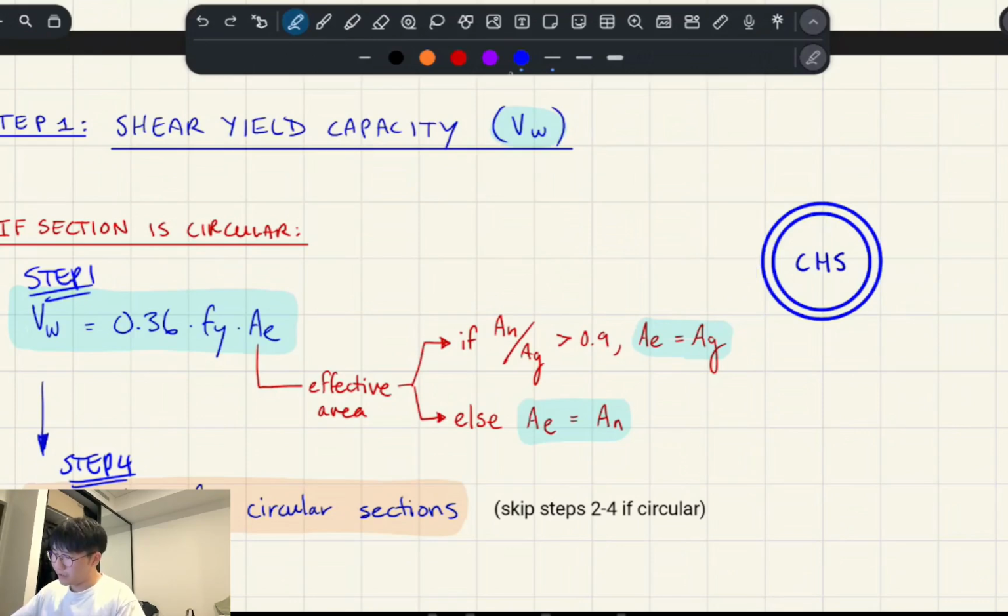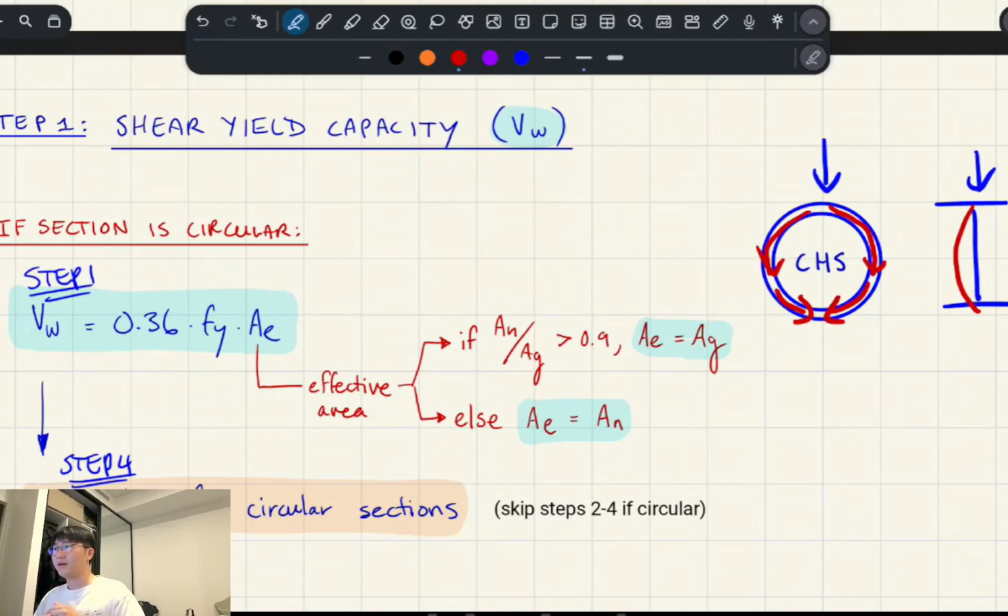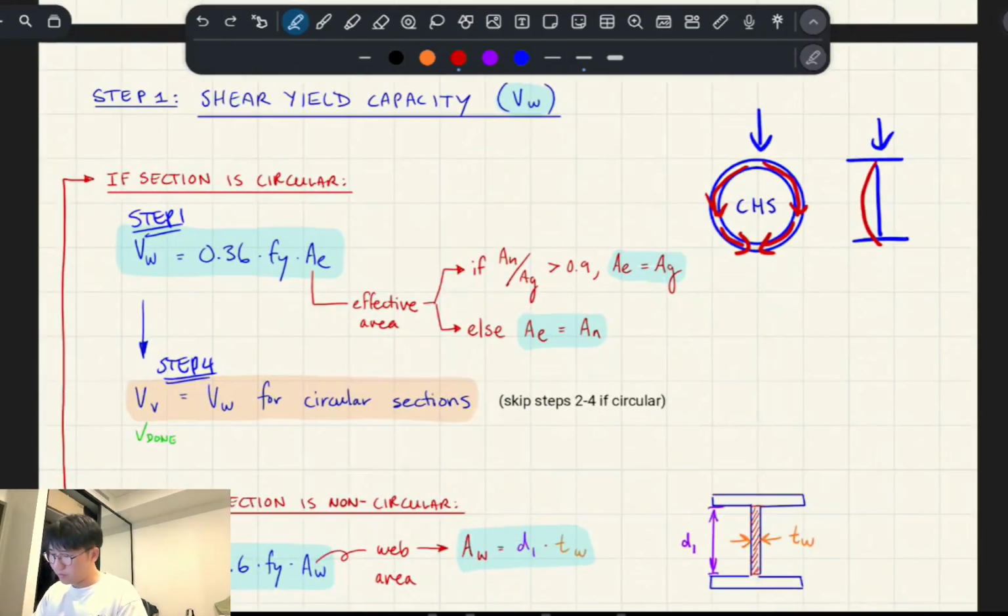hollow sections. And the reason is, if you think about it, which way is this going to buckle? Because for an I-beam, it can buckle to the side. But essentially the pressure has a better distribution, and there's better shear flow properties for hollow sections. That's circular particularly, so it doesn't really buckle.